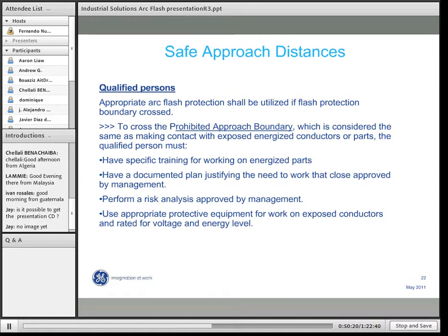Arc flash hazard analysis is a calculation procedure to determine the risk of injury from arc flash hazards. The bolted fault current is what you calculate during a short circuit study. It's the amount of short circuit current that occurs if you have a zero resistance short circuit, like if two energized conductors come in contact with each other. Whereas an arcing fault current is if the two conductors do not come in contact with each other and there is an arc through an insulating medium in between them.